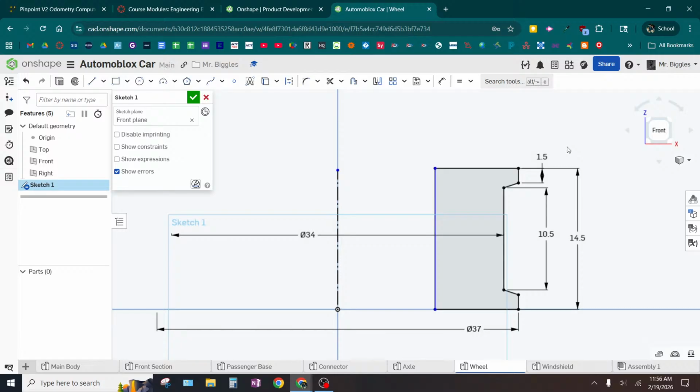The problem of doing this is you got to make sure that you're running through the fattest part of it, right? One way to do that is you pull these apart as much as you can, and that forces them to go to the widest part inside. Make sense? And I'm getting 29 point something, so that rounds to 30. So I'm probably going to do 30. I could probably do 29 or 29 and a half, somewhere around there. You do you, but you got to dimension either the diameter associated with this or the width of this. You got to do one of the two.